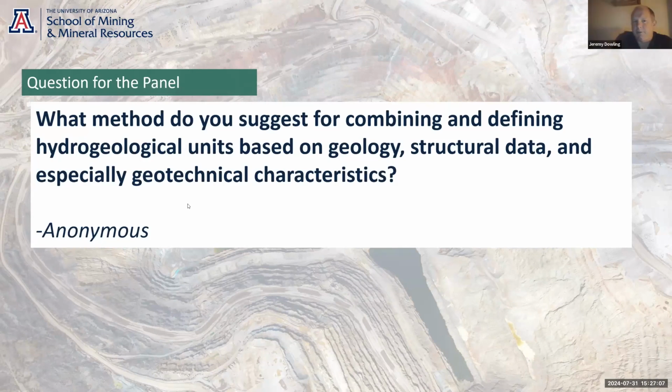Yeah, you can almost always enhance a hydrogeologic conceptual model through consulting with different geotechnical data sets for the same sector or domain. So I know Jeff and Lauren have covered off most of them. If there's a geotechnical fault register for the site, that has often got very useful information that can infer hydrogeologic characteristics.